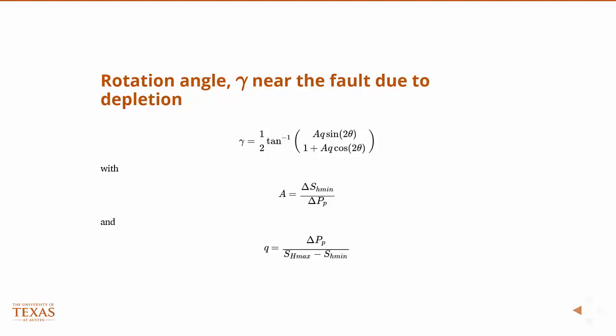SH max is going to, according to our estimation of how the stress changes, change according to what Zoback calls A, this stress path, times the change in pore pressure. Likewise, any shear stresses, because remember the shear stresses are proportional to the normal stress, right?